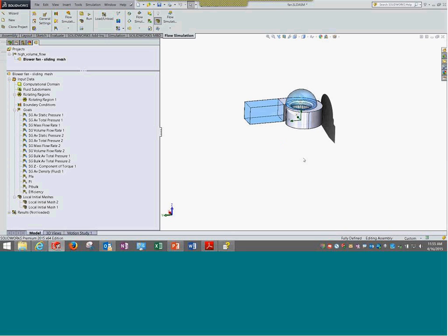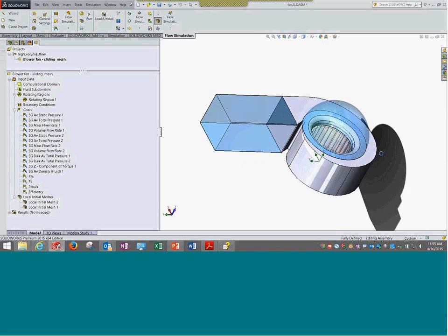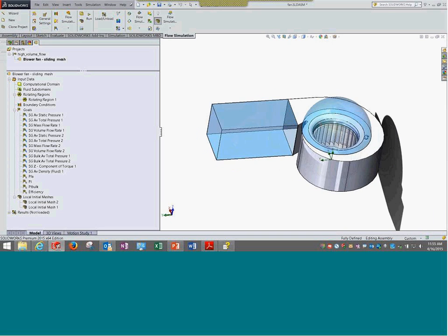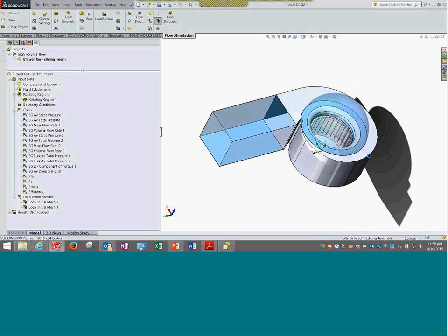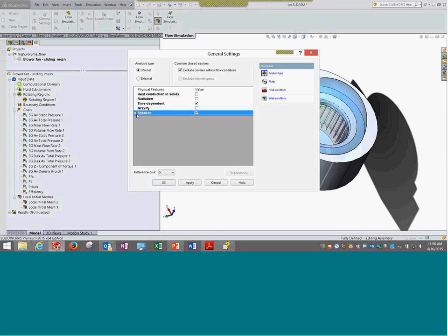But saying that, if you see the setup, there is nothing different. It is all the same process. The only difference is in the wizard or in the general settings, we are setting the sliding mesh option. That's it. And it can handle many more scenarios than the previous option of averaging. Okay. So we have the last 4 minutes for today.